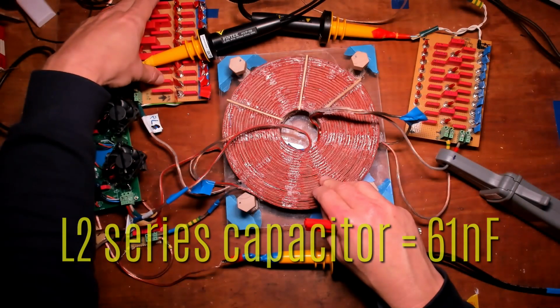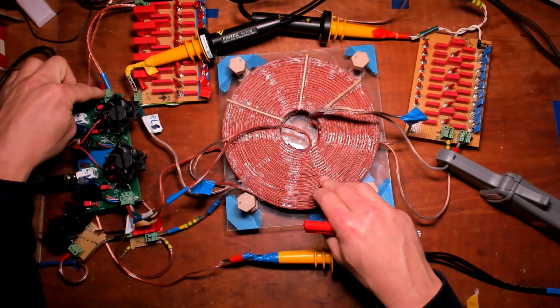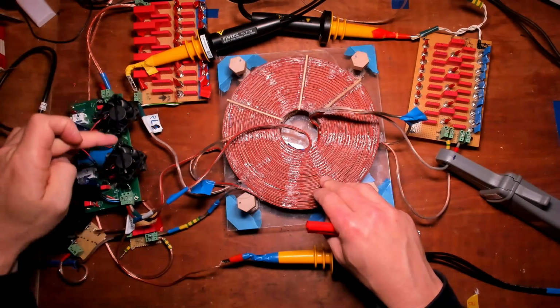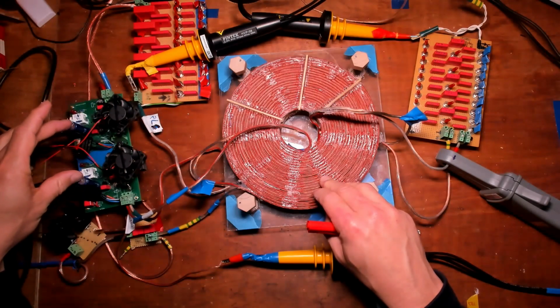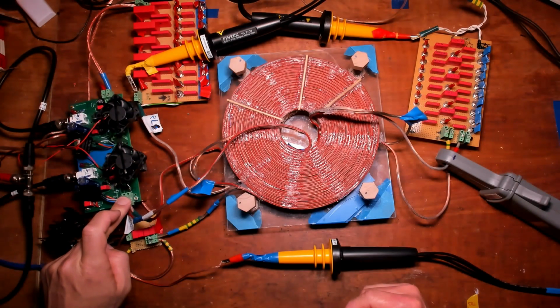Right now, this tuning capacitor is connected to the drain of the MOSFET. This is the MOSFET switching board. I've got 2 MOSFETs in series, and they are simultaneously switched by a 50% duty cycle square wave pulse. And the source of the MOSFET is connected to the L1 coil and the L2 coil.